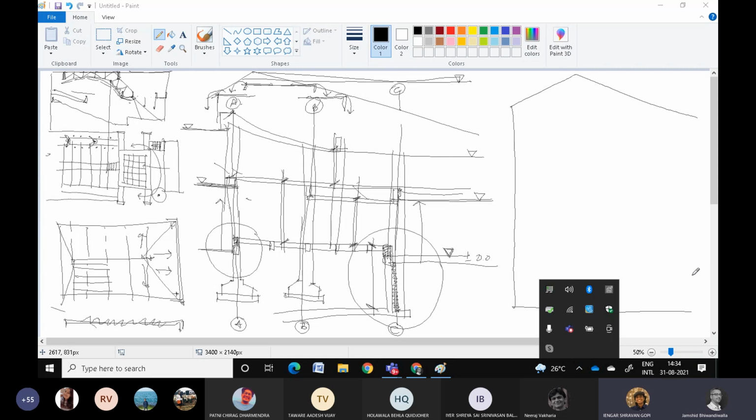No, you don't need to show everything. When a person looks at the section, he should be in a position to understand the overall structural system that holds the section. If you show everything, it may become too confusing. But I'll give you an idea. Suppose I show a beam, but I don't show its respective column that is a little further away in elevation. Then it looks as if that beam is floating in air.